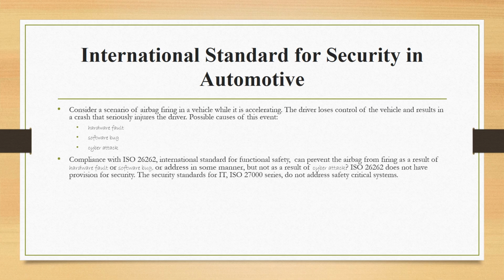Compliance with ISO 26262, the International Standard for Functional Safety, can prevent the airbag from firing as a result of hardware fault or software bug, or address it in some manner, but not as a result of cyber attack. ISO 26262 does not have provision for security. The security standards for IT, the ISO 27000 series, do not address safety critical systems either.